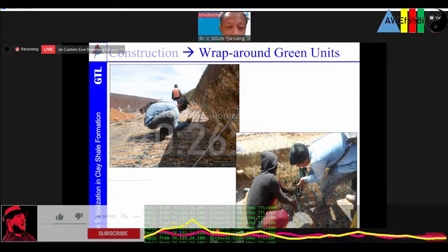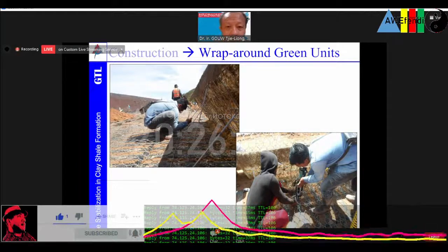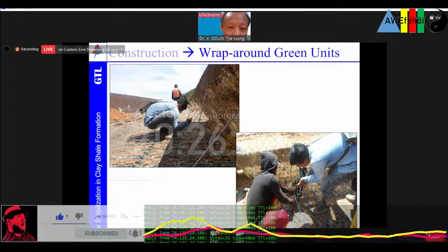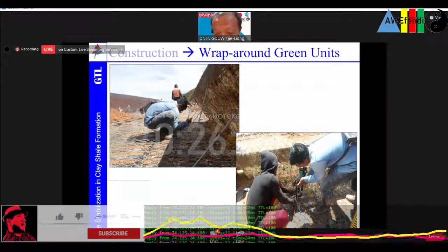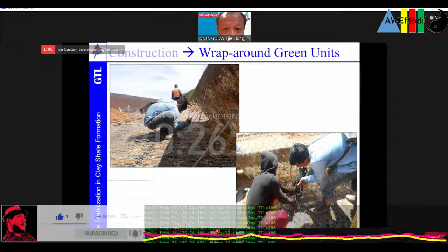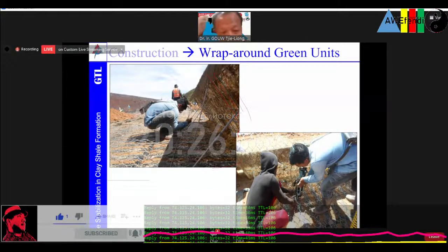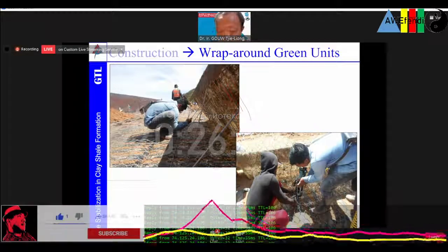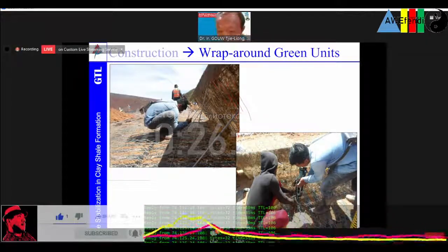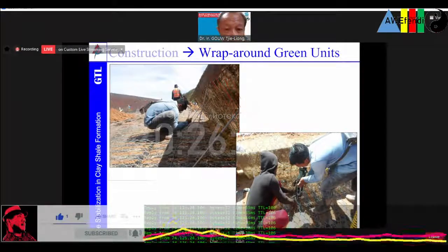After about 60% of the height, we put the so-called green terra mesh, just reinforcement by the wire mesh, so that grass can be easily grown over here as the facing, because the stress on the top 1/3 is not very high already. So we put it like this.